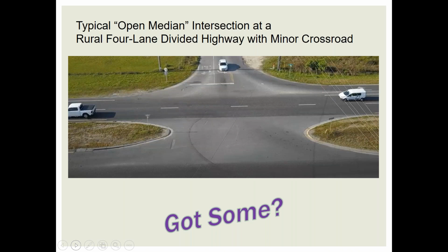So of a 4-lane divided roadway, the minor street intersection in a rural setting where we have high speeds. And the problem with these open median intersections is it's basically a free-for-all and just a lot of space to work with. And notice it's a typical median, not really wide enough to be treated as an area where you would have two separate intersections.